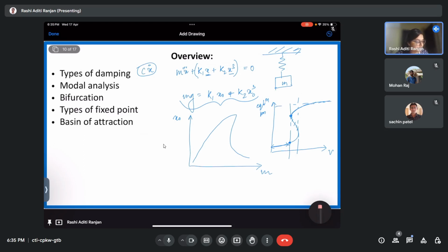And as you said about the dynamic case, as I discussed in the earlier class, if we have frequency here and amplitude here, in that case my system response should be something like m x double dot plus k1 x plus k2 x cube equals f sine omega t.